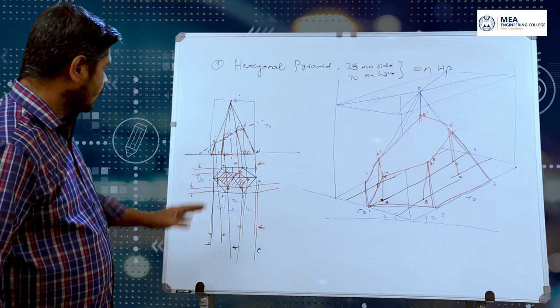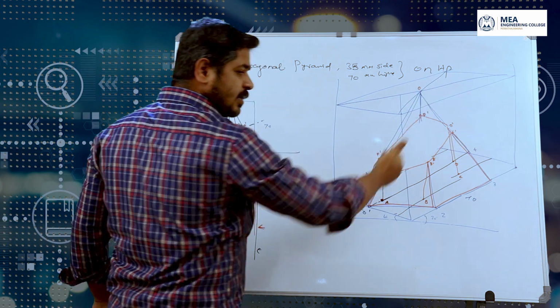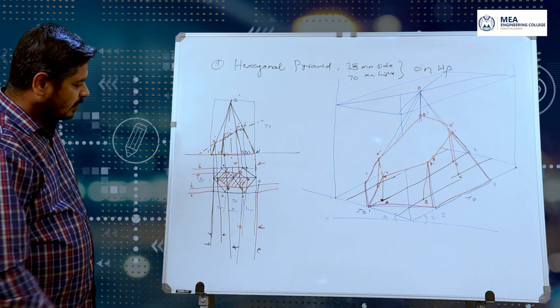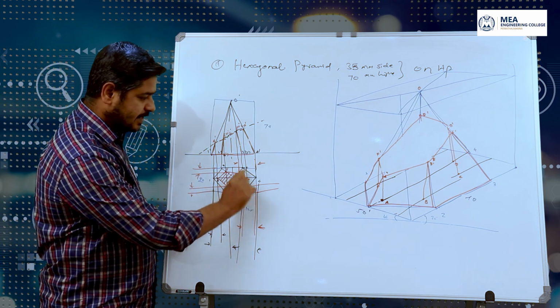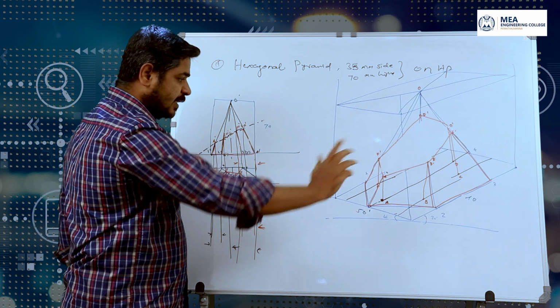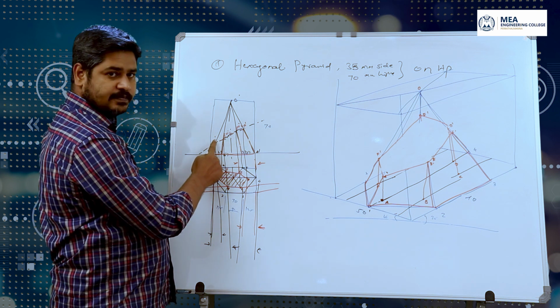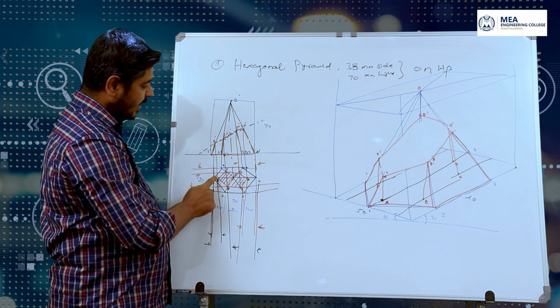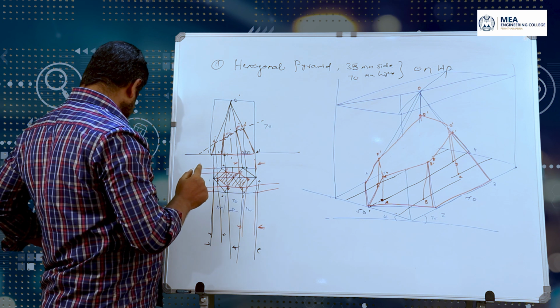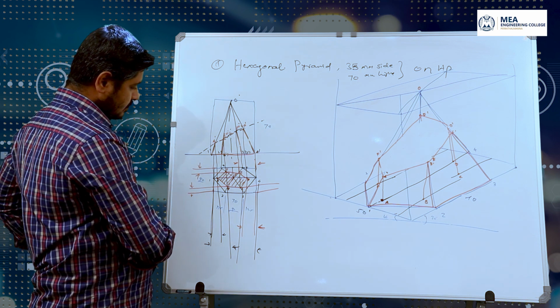Now is it clear? Now this is the surface, slant surface we have here. Okay, the procedure is so simple. First find the points A, B, C, D. Fix those points A, B, C, D on the base. Then draw the vertical lines. That vertical line definitely hits the slant surface. Okay, this particular point A hits the A dash here. Okay, you can do the same thing here also.